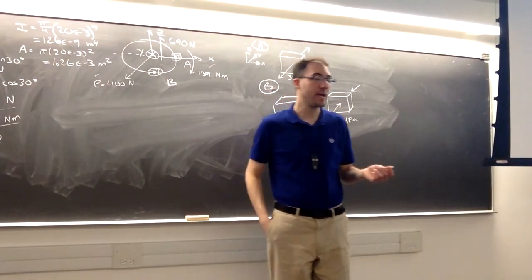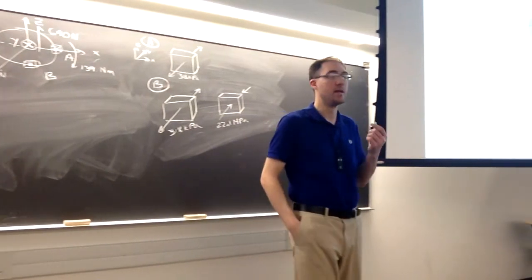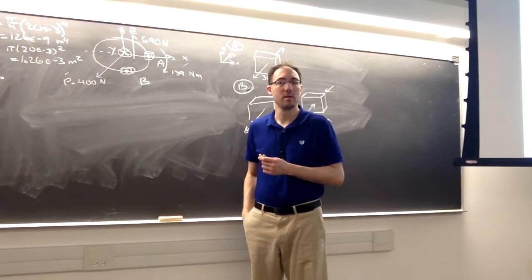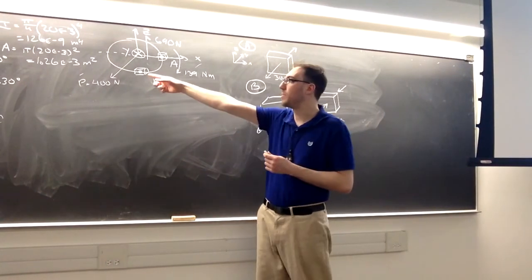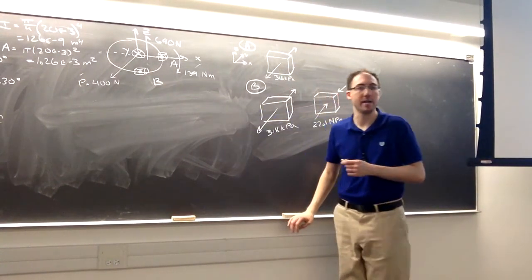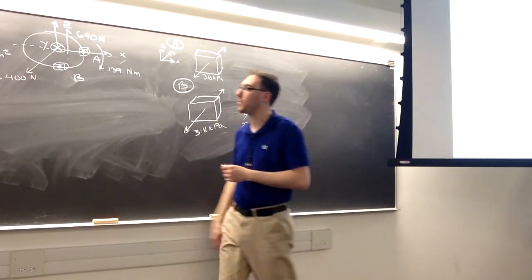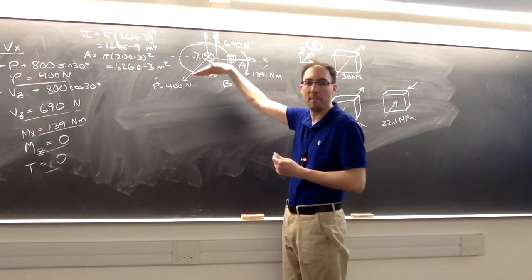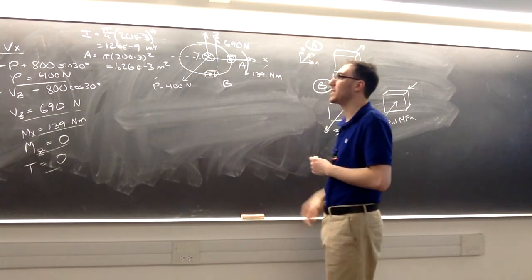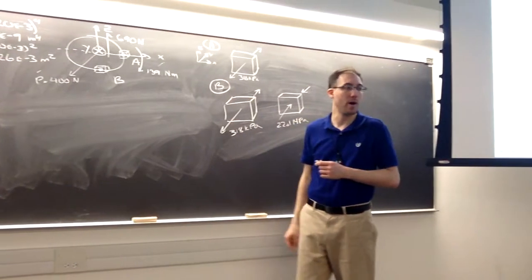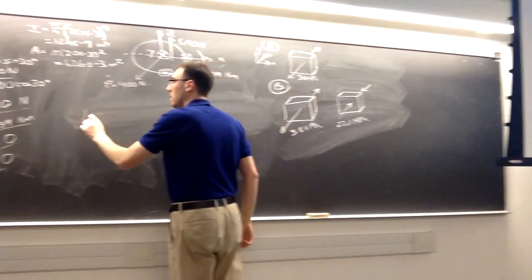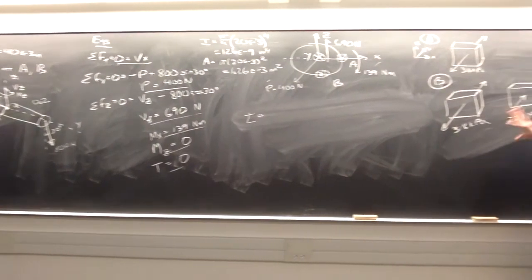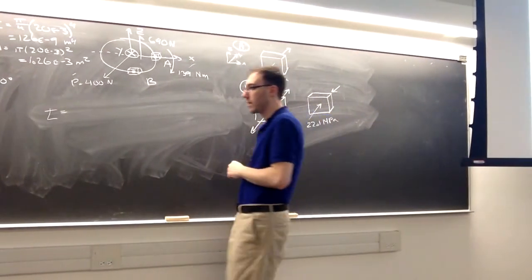Right. A will be. It's on the neutral axis, and we know that transverse shear stress is maximized there. Will B be affected by the 690 Newton shear force? No, because with respect to this neutral axis, it's at the bottom of the cross section. So B will not get a shear force, but A will. So only A is affected here. So B we're actually done with, but we'll hold off until the end, summing everything.